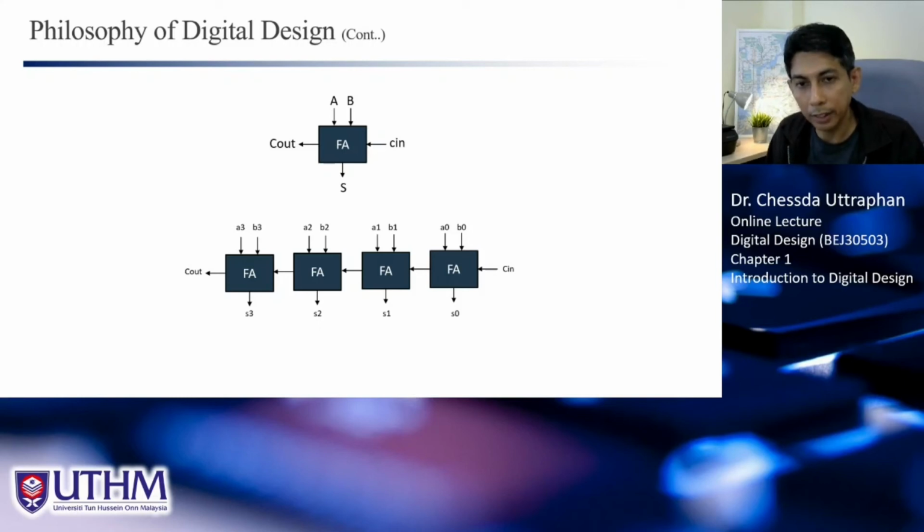All right. So for example, if you need one transistor to keep 1 bit, just for example. So if 8 bits, you have 8 transistors. All right. So if 1 million bytes, you just multiply 8 by 1 million. So you have 8 million transistors already. That's why you see millions or billions of transistors. How do people do that? Actually, it is this way, because the design is repeated, most of the time. So we can get the big circuit from the small circuit.